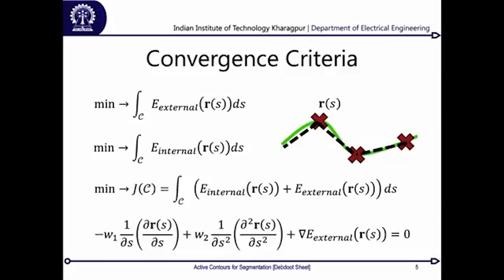Okay. Now this particular equation over here, which is my condition at convergence, actually acts as the major driver in order to design something called a solver. Now solvers are basically when you have a mathematical model in which over time you can iterate certain things and then come down to a convergence point. Now look into this one. What you initially start with is basically 2 points and 1 point interpolated somewhere in between. Okay. Now in the first iteration, this is where your energy criteria is found out.